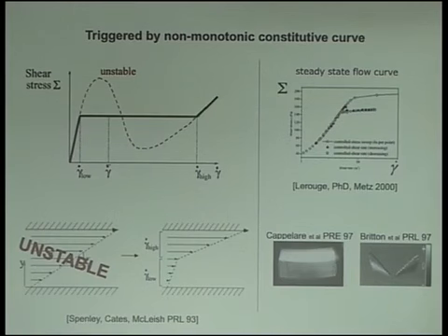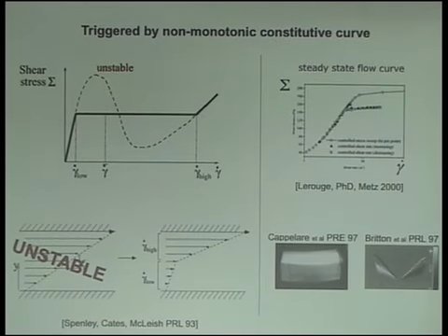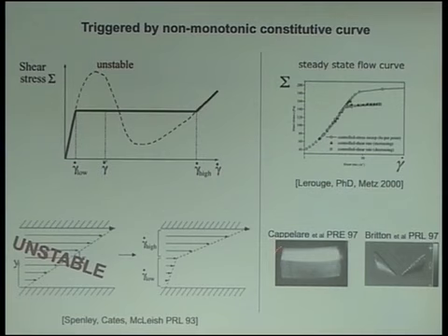Two of the earliest observations of shear banding. Actually I've drawn these theoretical cartoons as though we really have planar shear flow, but experimentally, usually the device has some curvature to it, so the way a fluid is often sheared is by sandwiching it between concentric cylinders and rotating the cylinder. Of course, if the gap size is small compared to the cylinder radius, we have a good approximation to this, and I'm showing just a small segment of those cylinders here. And so this is actually a flow birefringence experiment. We have a highly birefringent band here and a low birefringent band here. This is associated with the worms being orientationally ordered, and so these authors then interpreted this birefringent band as a high shear band.